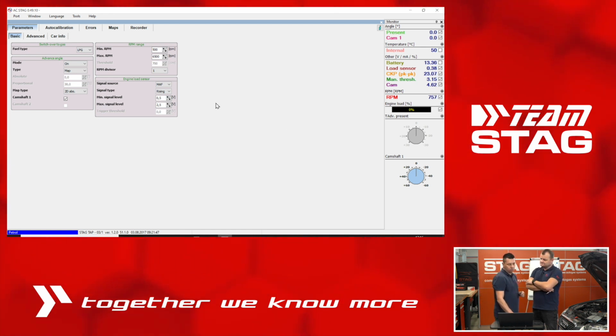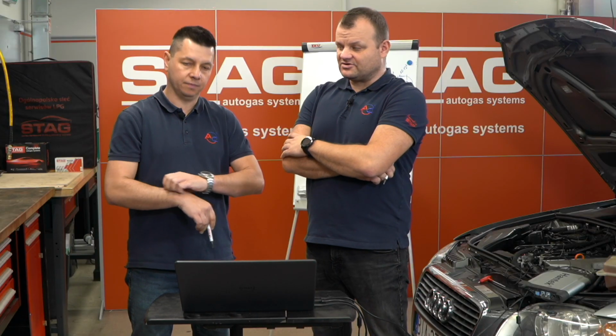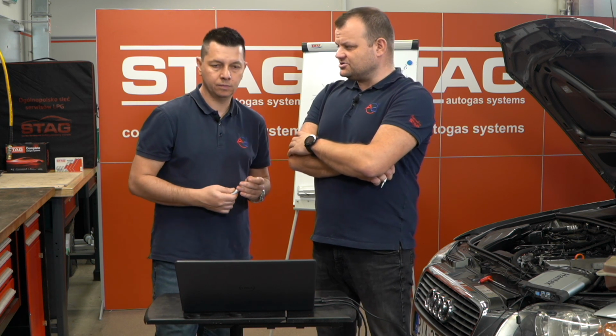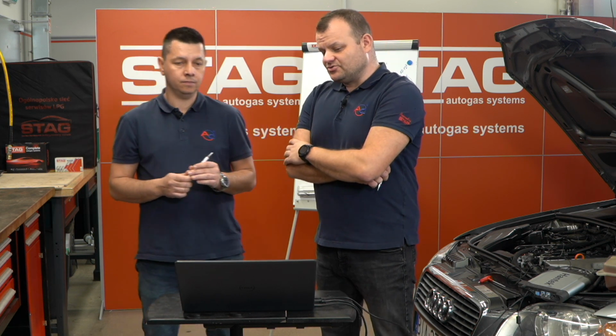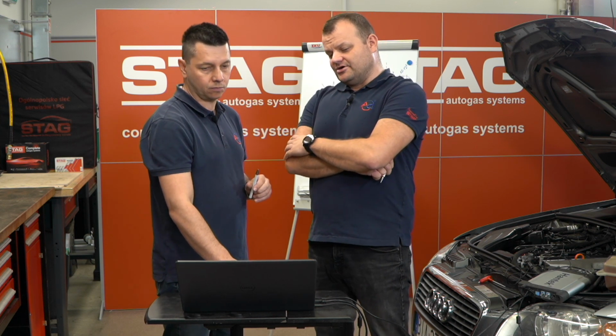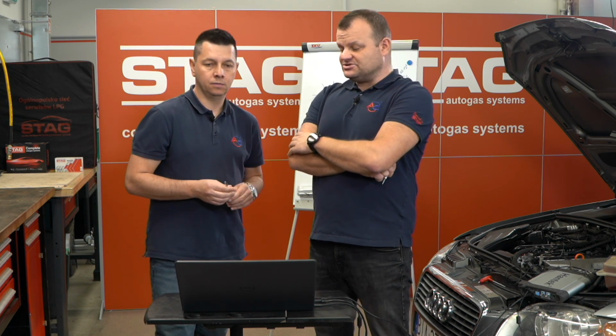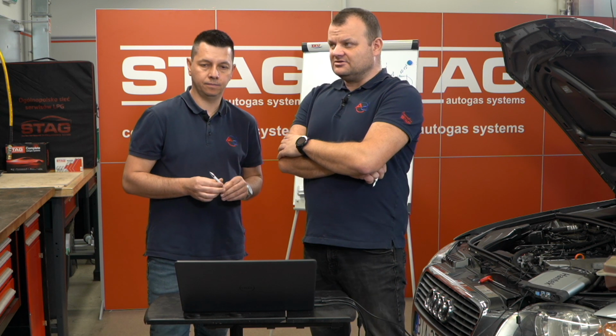Okay, after you set everything, you also need to calibrate the MAP sensor, the engine load sensor. That's why the timing advance is not present right here, because you need to also calibrate the load sensors. Yes, the load sensor is needed, of course, if you want to use different maps compared to the 2-dimension absolute. If you want a 3-dimension map, you can build the map according to the load sensor, and you can use the load sensor, the MAP sensor, or the throttle position sensor. It just lies in your choice.